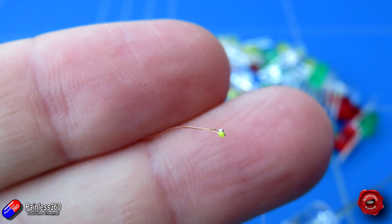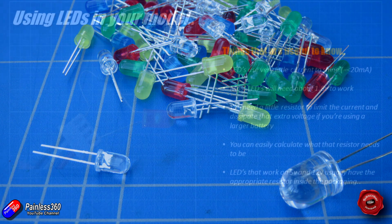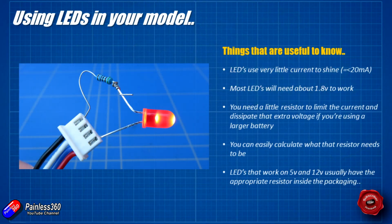Now the really nice thing about LEDs is that they're very efficient in turning electrical energy into light. So rather than the filament bulbs that we used to use in our cars, the LED uses a very small amount of power, 20 milliamps or 20,000th of an amp, to light up and to shine. Another nice thing as well is it needs a very low voltage to do that with, and average values are about 1.8 volts.